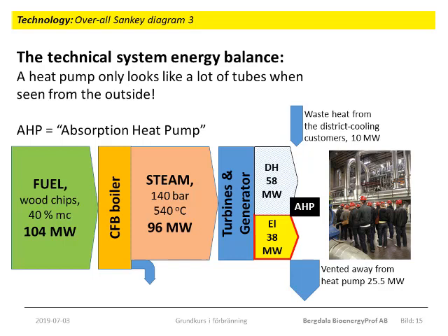The absorption heat pumps can take 10 megawatt surplus waste heat from the district cooling customers, and the COP is 0.7. So that means it needs approximately 14.5 megawatt district heating for its operation. And then it also takes about 1 megawatt electricity for the circulation pump. This all, total 25.5 megawatt, are unavoidable losses from the system.